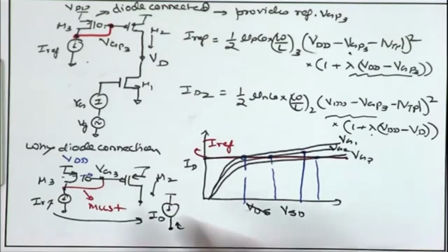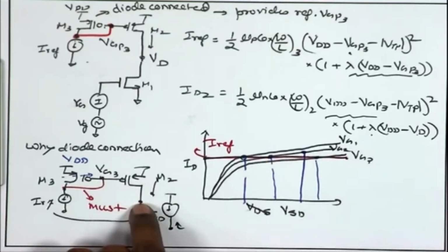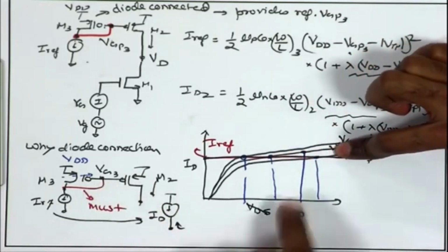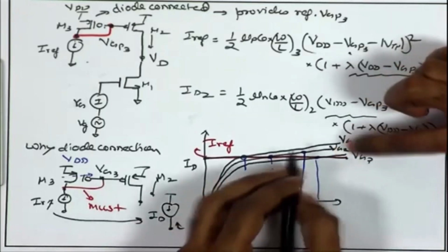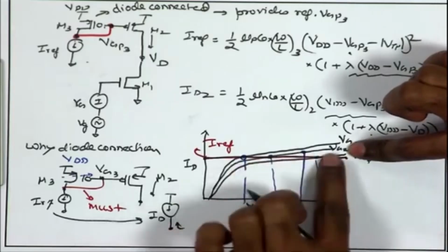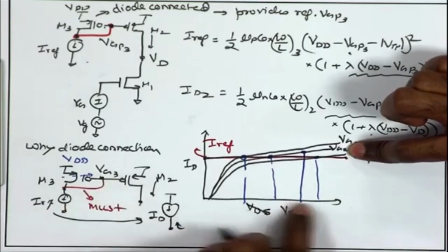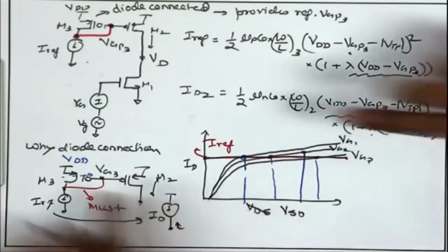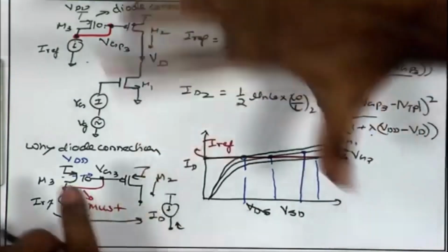And that is going to happen when we have the output characteristics such that the gate voltage is constant and we are observing the drain voltage. This is the curve when we have the gate voltage constant and then we are sweeping the drain voltage, right, VSD is changing. In that case, the change in ID will not be very high, because as long as the transistor is in saturation, gate voltage is constant and then you change drain voltage, you do not have much change in the current. So, that helps it behave like a good current source, close to an ideal current source.